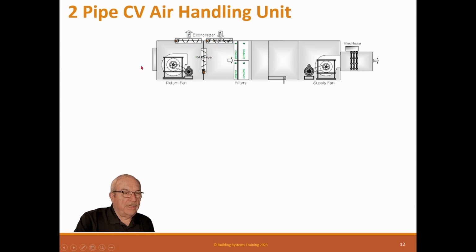So then the air from the building is pushed out by this return fan, and this supply fan sucks in the air from outside. And the reason that's important is because it has a balance component to it. So when you balance a job that's got economizers, you need to balance the air handler itself, not the grills, but the air handler itself, in both normal mode and economizer mode, because the pressure differentials can change. So we'll talk about that in a little bit.